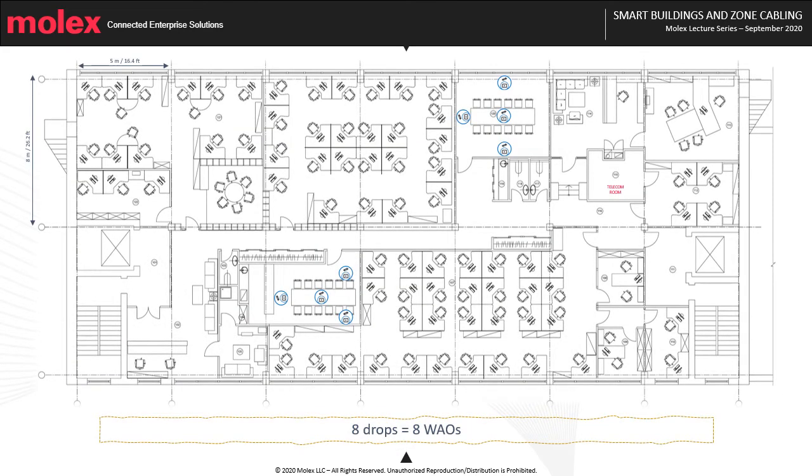We may now position our AV equipment outlets, and for our design, we have a total of 8 work area outlets to be used for AV applications. Okay, so we made that decision because these are meeting rooms and there is no real need or justification for 2 work area outlets per audio video access point.